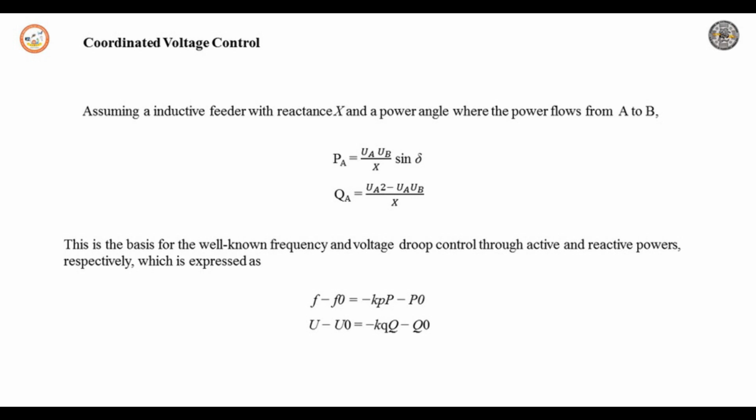voltage profile. If two identical units are connected close to each other, and both are equipped with voltage control that takes the same terminal voltage as an input, they would provide exactly the same power to compensate the terminal voltage decrease.